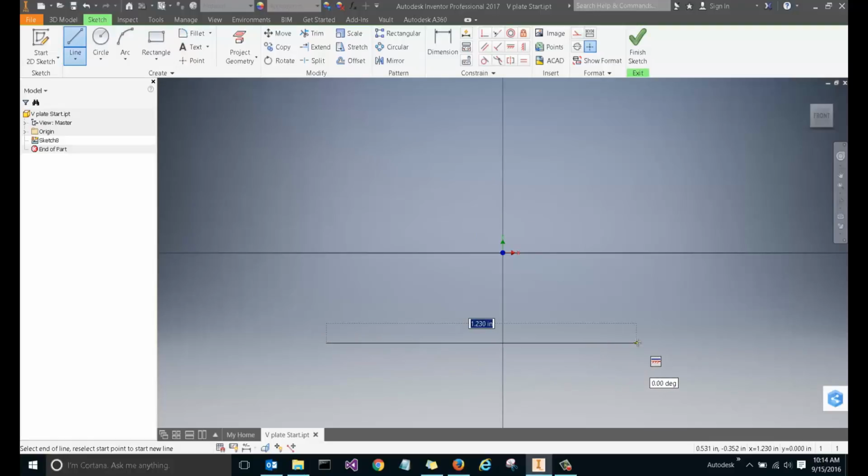And here you can see the horizontal glyph. It's just kind of showing off there. That's the inferred constraint, if you will. We'll pick a point and then we'll drag it up. What you're going to see here is it goes to perpendicular. Again, setting priorities, perpendicular and parallel are over the horizontal and vertical. Again, we'll pick that point and drag across.